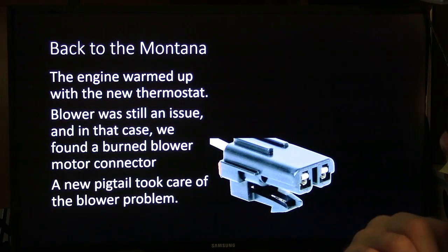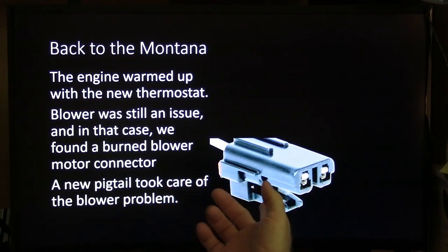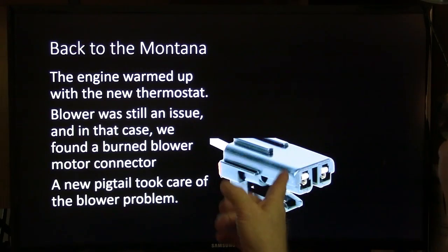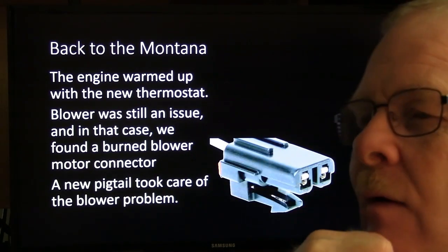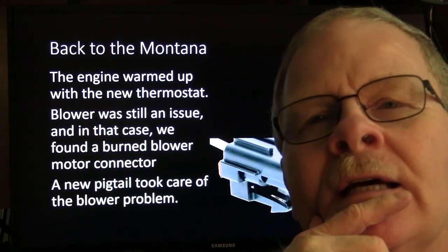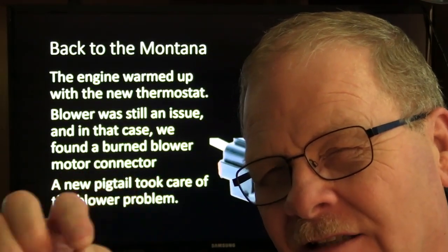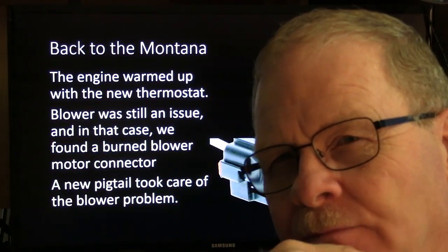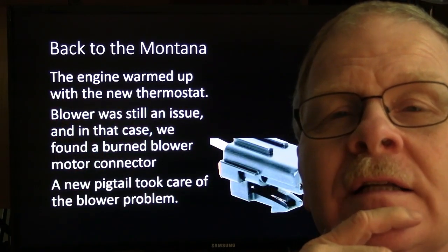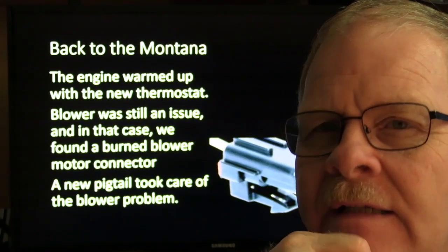Now, the Montana, when the engine warmed up with the new thermostat, the blower was still an issue. And this is the blower connector. That actually is a new one. The one that was on the blower was burned up. Sometimes you can take a pocket screwdriver or something and scratch the oxidation off the terminals in the blower. To be perfectly honest, the smart move and the smart play is to go ahead and replace the blower and the blower pigtail.